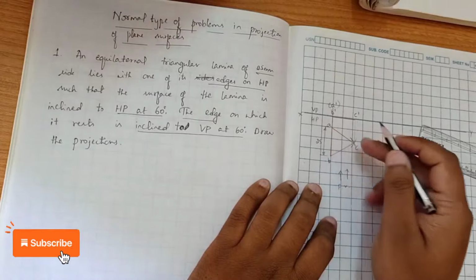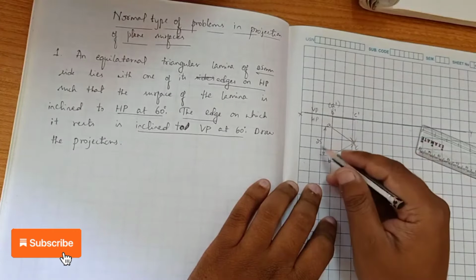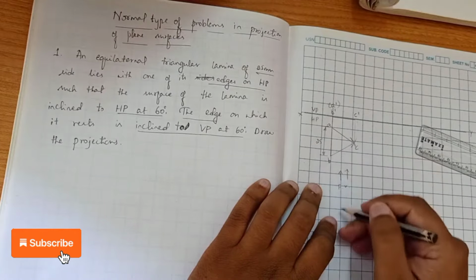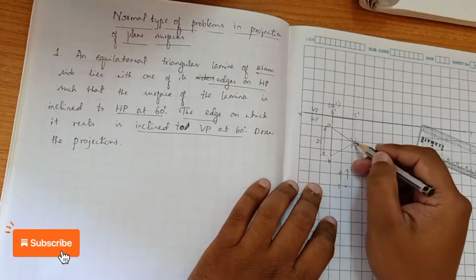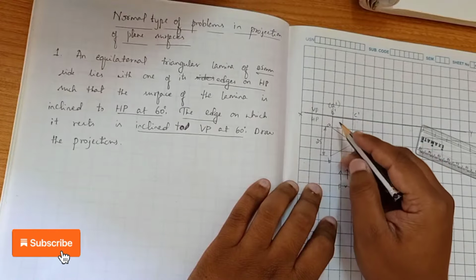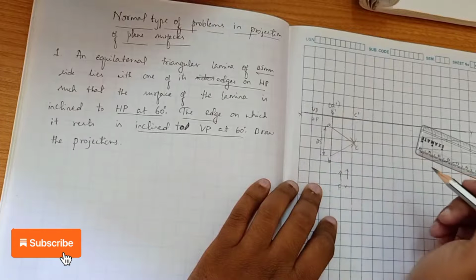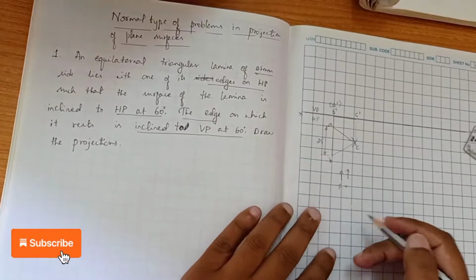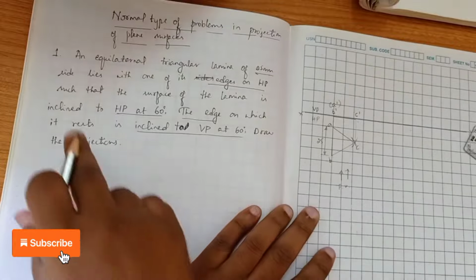When we construct a triangle, we get the same dimension of 25. So when we project the front view, we are able to see only this edge BC. That's why B dash C dash is written without brackets, and A dash, which is not visible, is written within brackets. Okay, so this is the first position. Now you see the question,